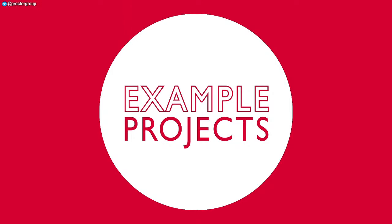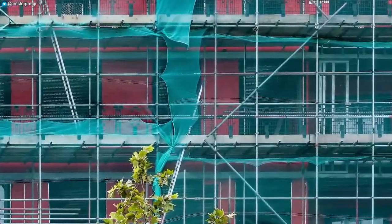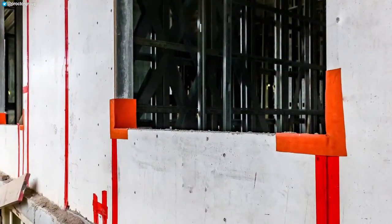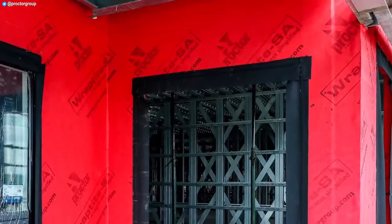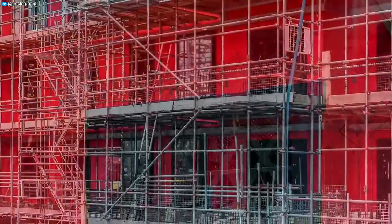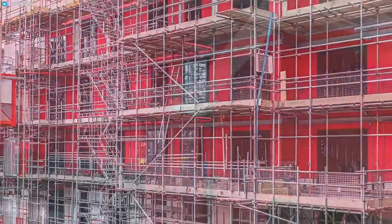The first of our example projects is a new build apartment development where the original design called for an air leakage rate of 5 and used rigid PIR foam insulation over a concrete frame. After the tragic events of Grenfell in 2017, a priority for this project was to replace the originally specified PIR foam insulation board with incombustible mineral fibre. This introduced a substantial shortfall in thermal performance, which the designers were not keen to offset via increased thickness. Specifying Raptite as their air barrier membrane allowed the designed air leakage to be reduced from 5 to 3, going some way to offsetting this increase in thickness.